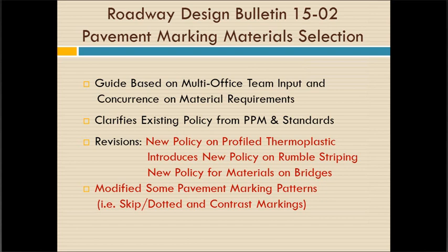These are some of the major revisions that you need to know. When you get into the material selection, the first thing you're going to notice is profile thermoplastics in section 701. Profile thermoplastic is nothing more than renaming what used to be audible and vibratory markings. And so we're going to go over how profile thermoplastic is used in relationship to rumble striping.